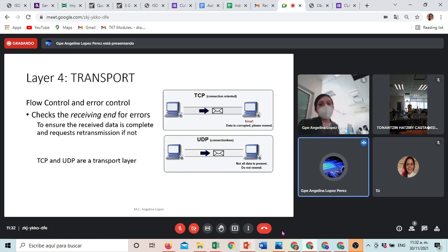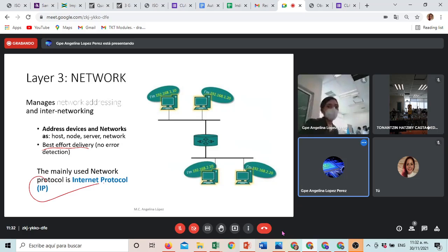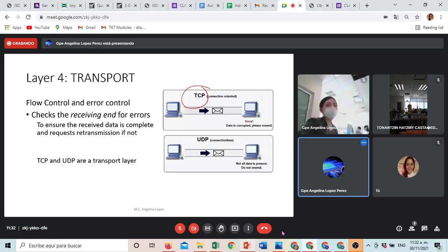So one famous protocol for transport is TCP. Okay. So when you connect your computer, when you are connecting by first time your PLC to your computer, one of the protocols that are on the list besides MPI is TCP/IP. Do you remember? Well, TCP/IP is the Internet Protocol with TCP of transport. So it's two layers of the OSI model, the ones you are selecting.